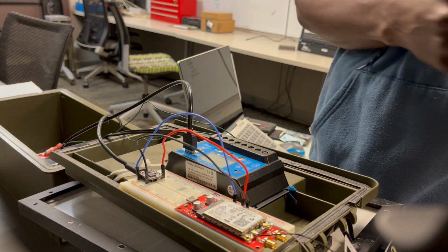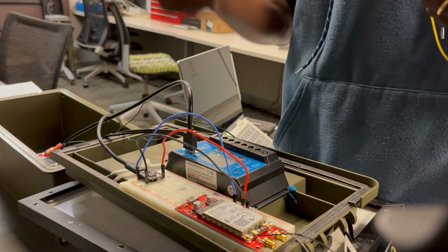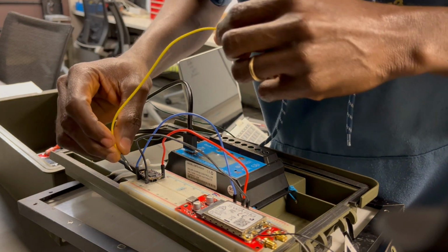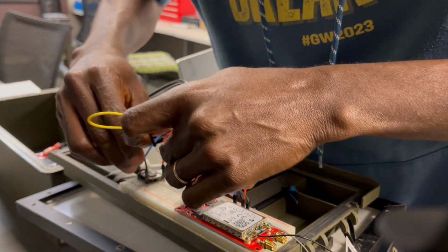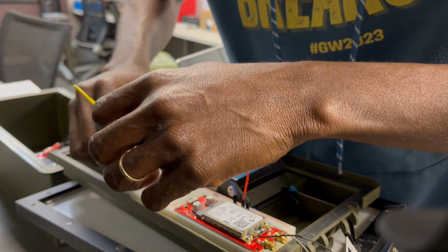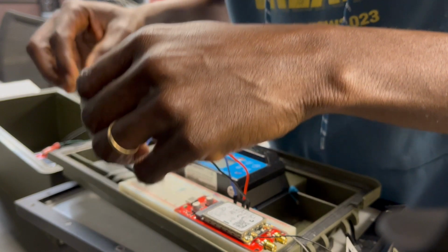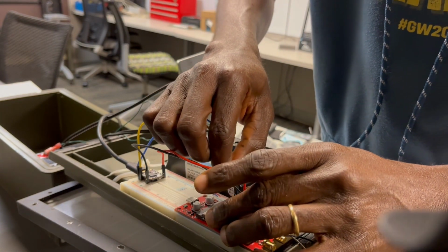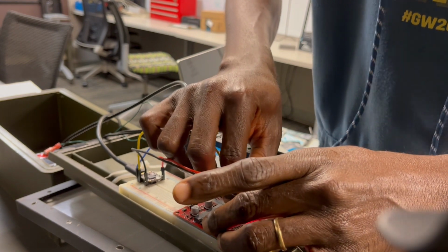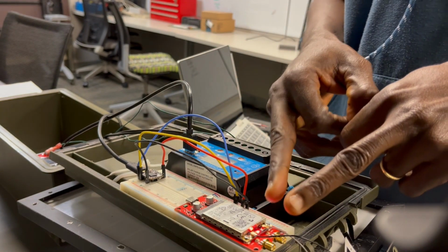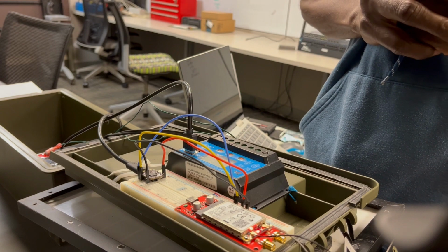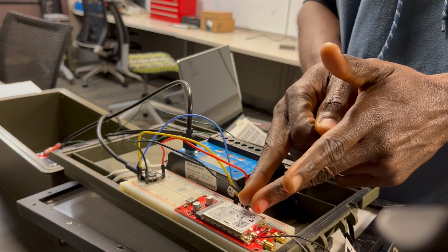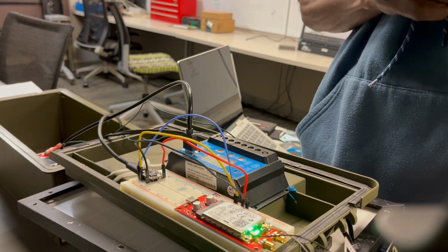And then I need to use the QT-PY to power the Swarm board, which is also a solution that Swarm recommends or approves of. So I'll connect the VIN ports, which is also mapped here, straight to the VIN port over there. And voila, you can see the Swarm board has started blinking. So this time the QT-PY is powering the Swarm board.